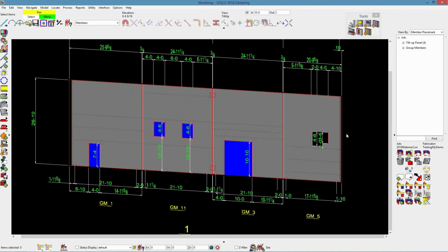To cover this real quick, we talked about up here on my floating toolbars that if I've got orange puzzle pieces, these are my components. When components are added to the member, I can either edit the member to modify that component, or I can change my selection filter to custom components to double click on it and edit the connection component so it updates.